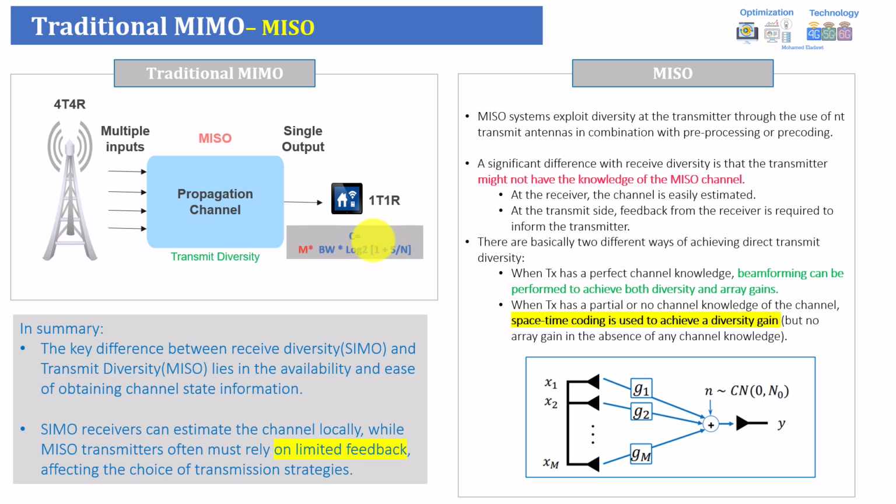There is one very important point I mentioned at the very end of the SIMO part: you should understand that there is something called channel knowledge. What does channel knowledge mean? For example, the receiver knows about the propagation channel, whether it is very poor, what the condition of the channel is, through reading the pilot channels. Pilot channels can be DMRS or the cell specific reference channel. So it understands very well the channel knowledge, or the propagation channel in general.